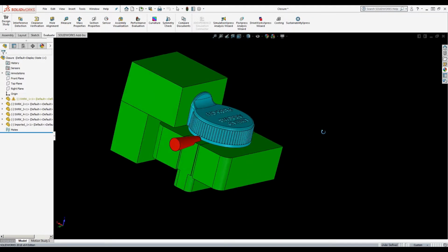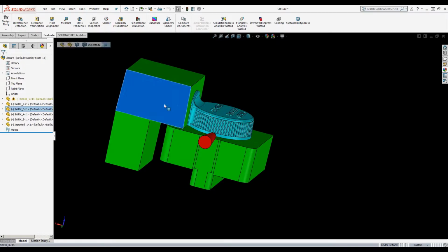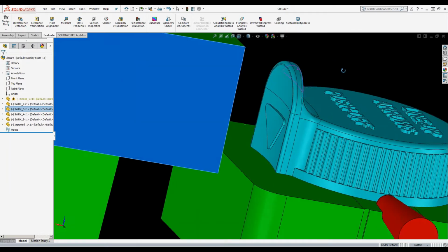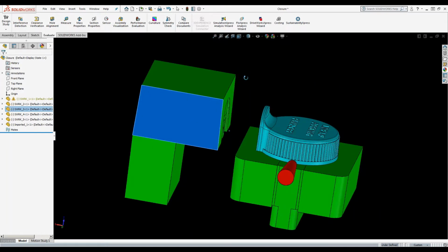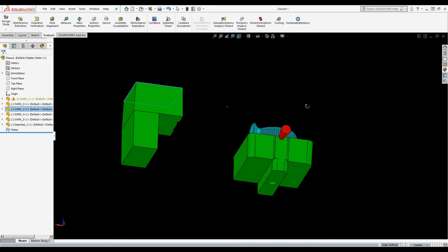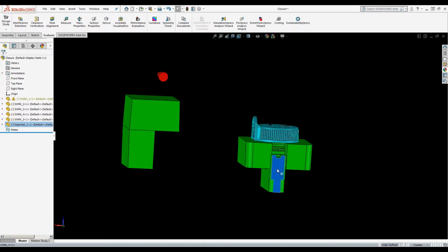So here's essentially the portion of the mold that makes this part. We have this loose piece here that creates the arrow indicator on the side that we looked at first. Then in order to create the features on the inside, it's almost like a puzzle. Let me just remove that out of the way. This area of the tool would be stationary in the core and would eject out from the part. Stay with the tool, part would eject out with these two loose pieces still intact in the part.